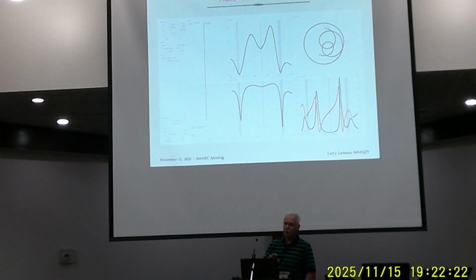So this makes it look a little more like that $25,000 one now. You've got 4 windows and they all have their own scales now. So the SWR goes from 1 to 10, the return loss goes from 0 to, I don't know what, negative 30 dB. So they all have their own scales now, so you can see all of those simultaneously. And you just can't do that with the little thing itself, but the data is all there.